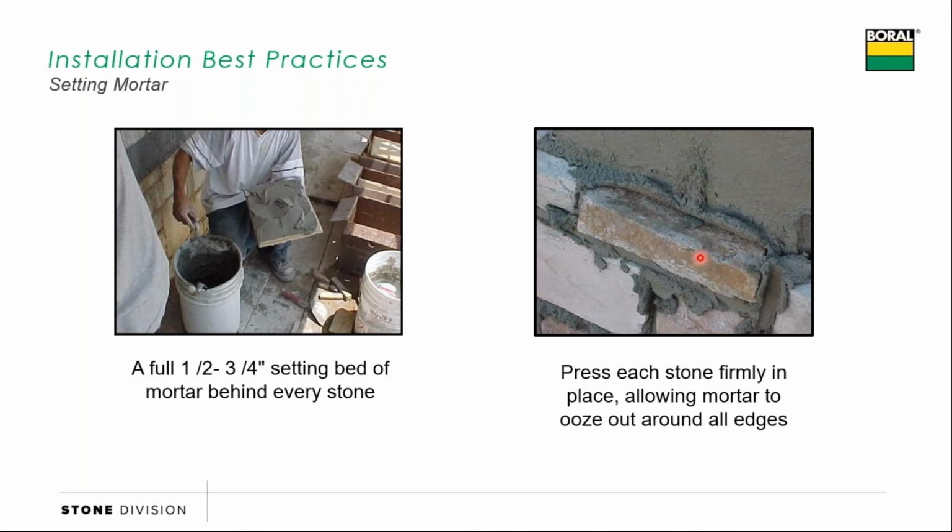When it goes up to the wall, we're going to move that stone as we set it left to right or up or down so that mortar squeezes out around all 4 sides. Probably should look a little bit like this. This is probably a little bit messy. If you've got an eagle eye and notice that there's no lines in here, well done, you get a star by your name.